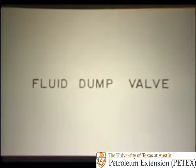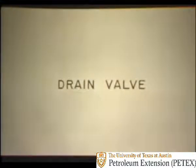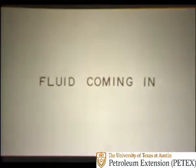So if you have the problem of low level, check for these three things. 1. The fluid dump valve, to see if it is hung in the open position, or perhaps the trim is cut out, allowing the fluid to be dumped even with the valve fully closed. 2. Check the drain valve to see if it might be open or leaking. And 3. Check to see if there is fluid coming into the vessel.